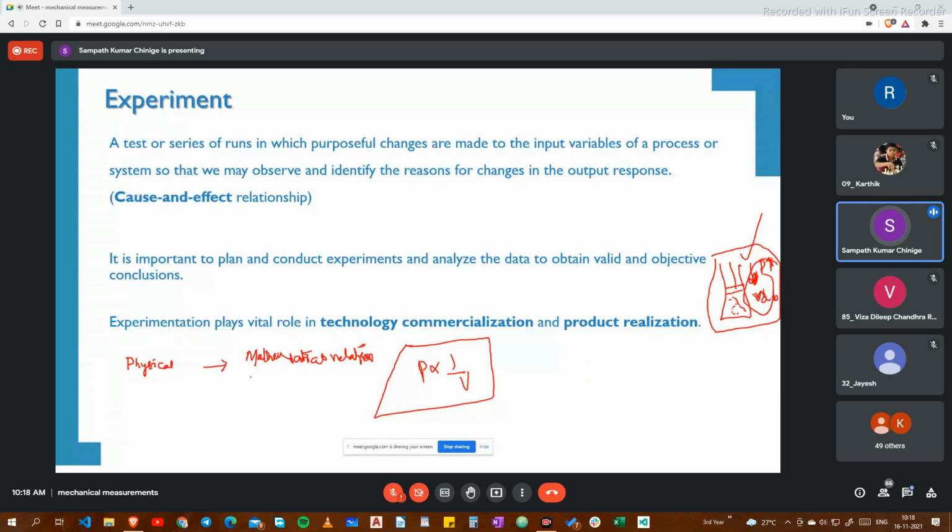Whatever we are following here holds when temperature is kept constant. How is the temperature kept constant? How do you ensure it? By insulating the sides. This is the critical part that you have to carry out. In this particular experiment, your insulation has to be absolutely adiabatic. It cannot allow any transfer of heat so that this relation holds true.